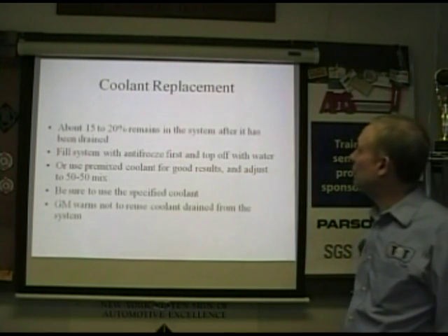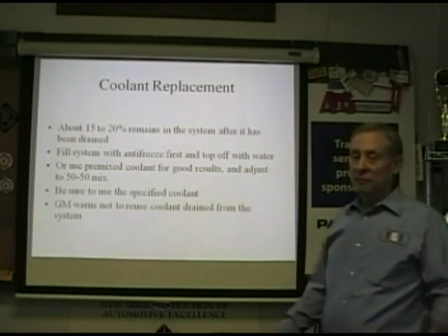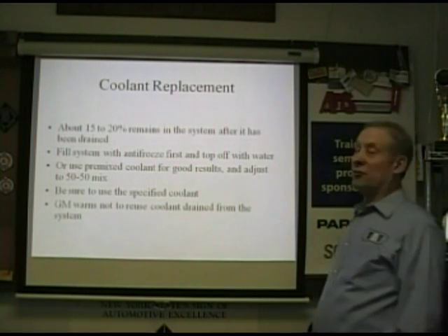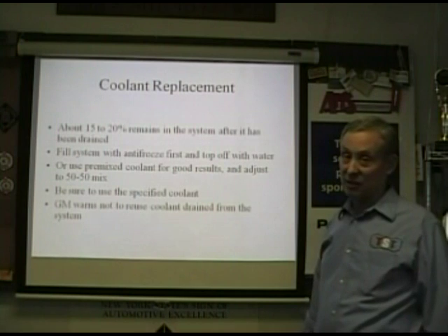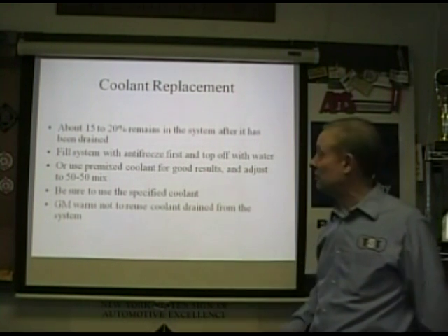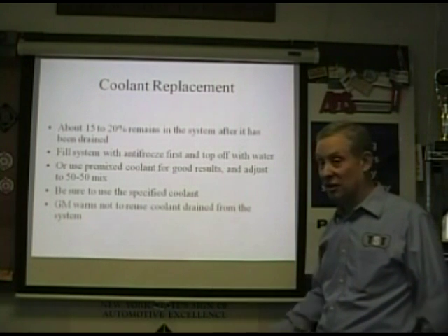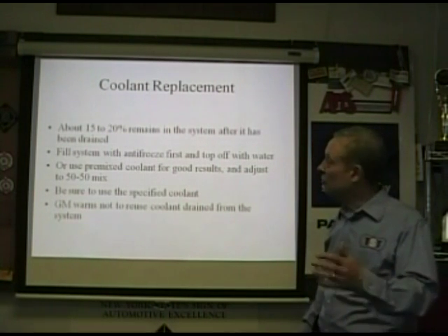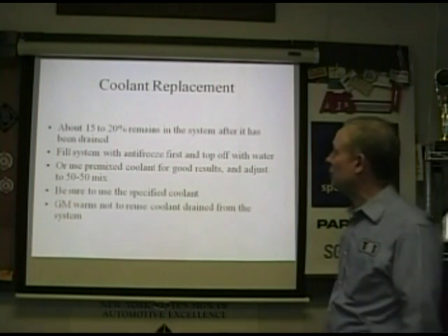Yep. Okay. Coolant replacement. 15 to 20% stays in the system after it's been drained. That's why I say you've got to really clear it as much as you can. Clear it till you've got a lot of water in it. Run it a few times. Be aggressive. You have to be able to charge for this. You have to sell the customer on it. Don't do the quickie job, because you're not going to get what you want out of it.